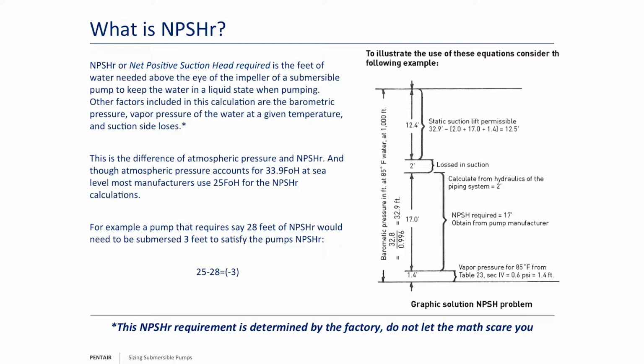Now, one of the things I would tell you, be it a submersible that we're speaking of, be it centrifugal, no one builds a perfect pump. If anybody ever told me they built a perfect pump, I'll tell you that person's a liar. And I'm not being mean, it's just a fact. We're human beings. Your pencil has an eraser because you make mistakes, so does mine. That means that when we build these pumps, there are imperfections. The parts have to have gapping in order for them to spin freely with the water lubricating them. You have machining errors. Machining might not be perfect. Assembly errors, you might not set these properly. You have wear and tear. So no pump will draw from 33.9 feet.